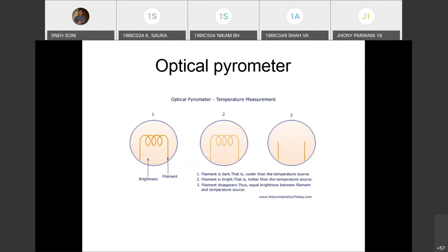सर जब हमें वो फिलामेंट दिखता नहीं है तब क्या रियोस्टेट का पोजीशन नोट करना है? आपको रियोस्टेट का पोजीशन नोट डाउन करना है, and at that time whatever resistance you are connected in the rheostat, it's a variable resistance, right? So because of that the current will vary through the filament. So at that point when your filament is completely disappearing and you cannot see it, you have to stop and you have to monitor the current value from the circuit. Am I clear? Yes sir, thank you.